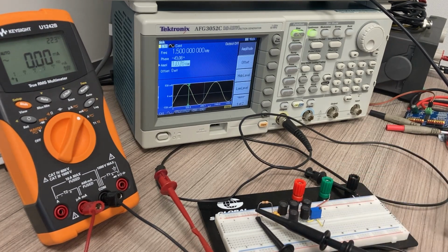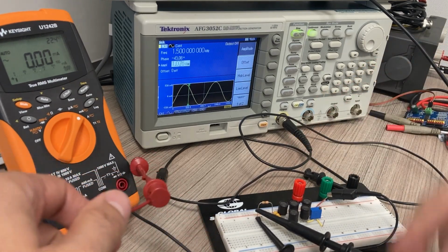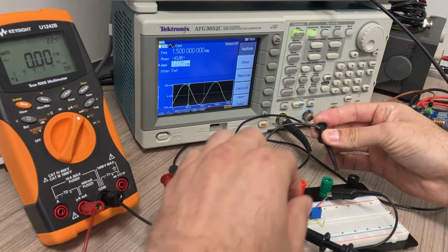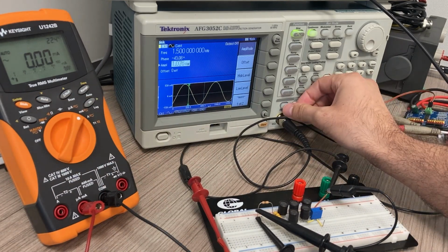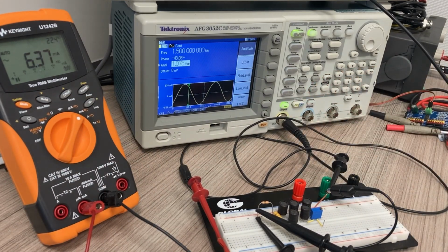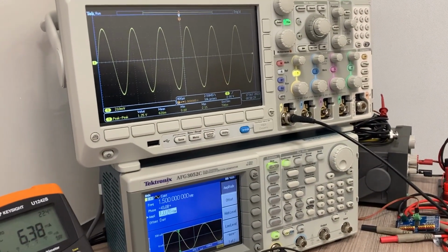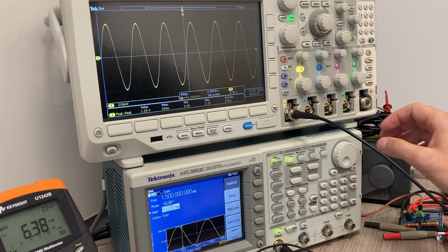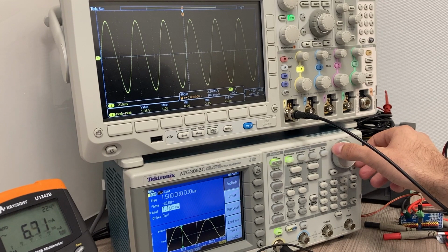And what I'm going to use the oscilloscope for is to make sure that I'm actually getting the intended voltage. Okay, so this looks a little complicated here. According to my Thevenin, I needed about, what was it, 1.52 or 1.53 volts. So let me shift this a little bit until I have 1.53.